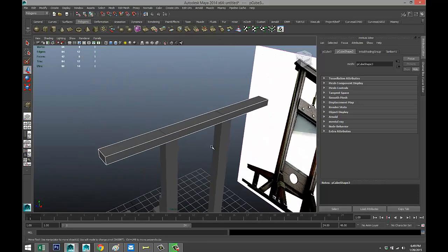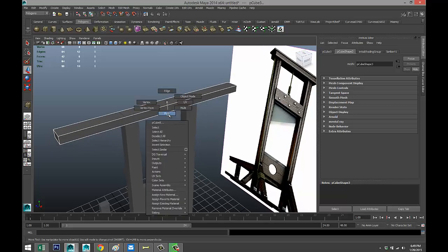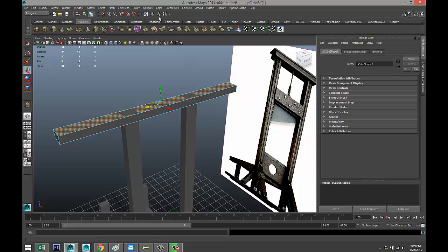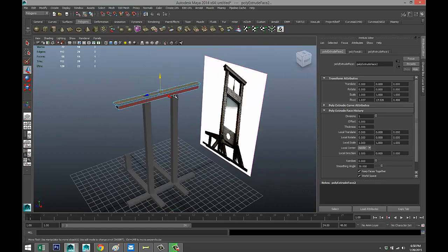We're going to focus on this guy. Let's give that a little bit of shape, if you will. Right click face, edit mesh, extrude. We're going to pull that up and hit R and scale that out. Hit G to repeat and W to pull up again, just to give that some shape.